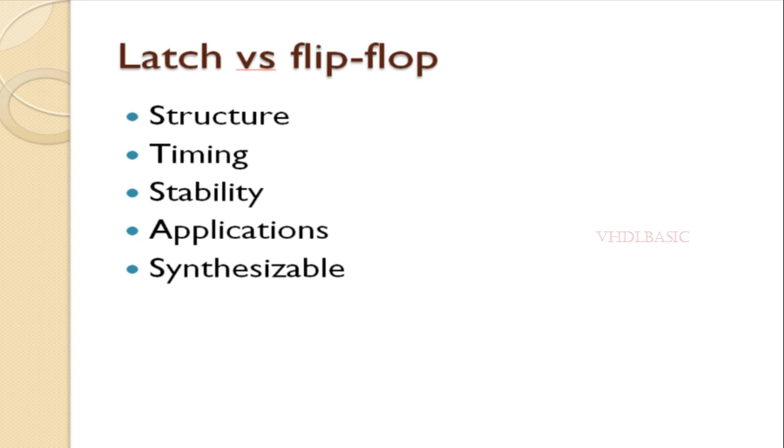Latches and flip-flops both can be synthesizable. When it comes to meeting timing, latches will be a little tough to meet timing in STA analysis. In the case of flip-flop, it is synchronous with respect to the clock. So the STA will not cause much problem when you are using the flop in your design.